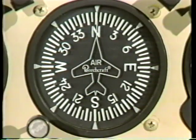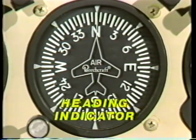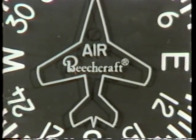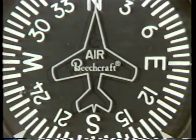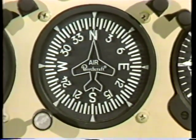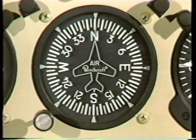The heading indicator is the last of the three gyroscopic instruments. This is not the airplane's magnetic compass, which we will explain shortly, but rather an instrument designed as an easy-to-read indication of direction, free from magnetic compass errors. Most heading indicators show an airplane symbol on the face, which is over a 360-degree azimuth card connected by gears to the gyro itself.